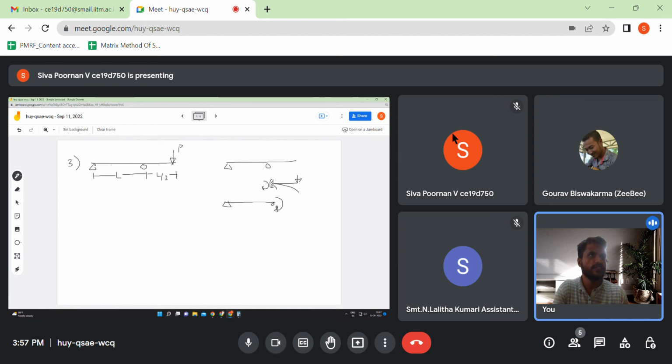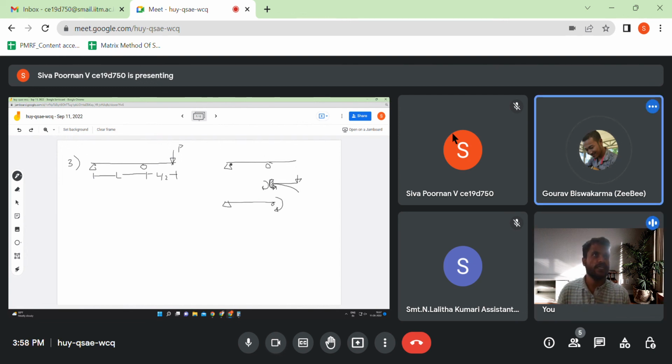But when I say it's a fixed end, we don't need to have the rotation be zero there. What I mean is that there will be a moment there. So we can have a non-zero slope there, but we know there is a moment, so because of that moment it will hog here. It will be something like this, right?